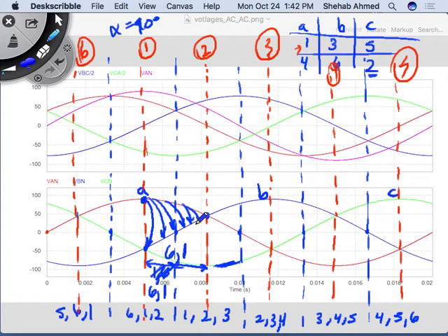Which device am I asking to change the polarity of current through? So 6 is the lower on phase B, the return, right? Here I provided a gate signal for thyristor 2, right? Is it easier to return from 6 or 2? 2 is phase C. It's the lowest, the most negative, right?